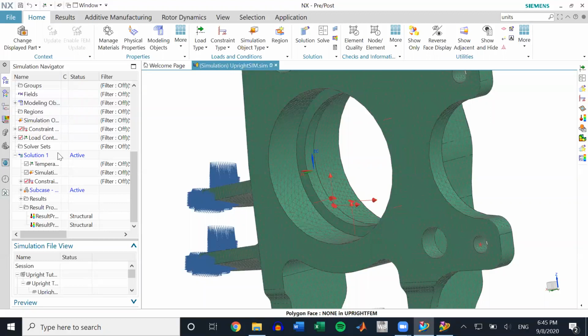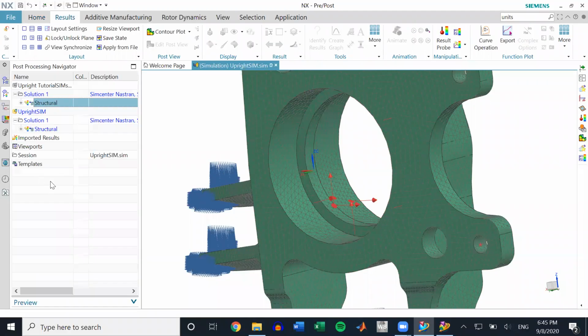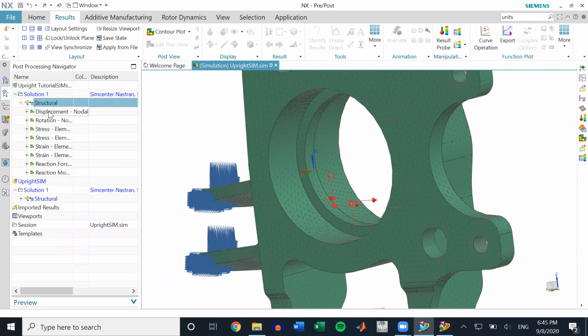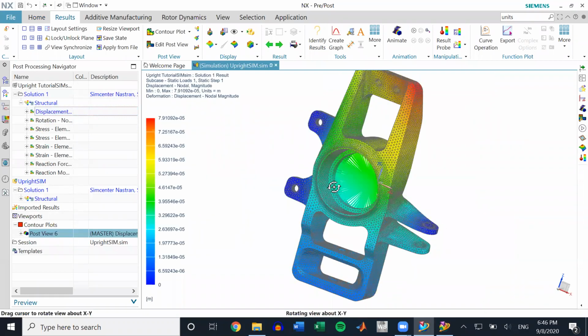And just, I guess, a note that I didn't clarify each time. Within each rigid body element, the mesh associated data had different degrees of freedom selected for each different type of rigid body element. So it just varies based on the type of load you want to apply. So that's just something to keep in mind. So this is all set up and I've already solved it. So we'll go to the result and just show you the displacement.